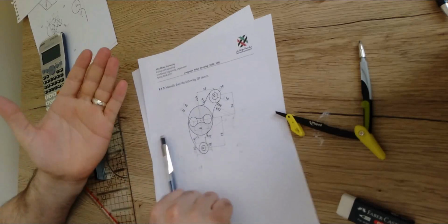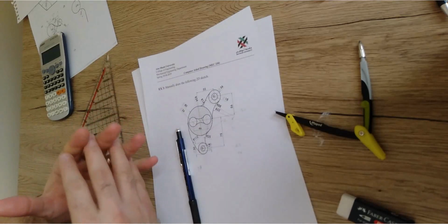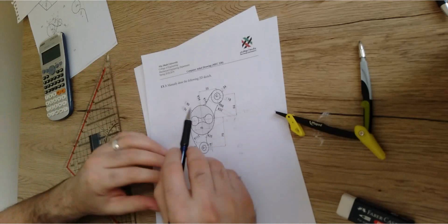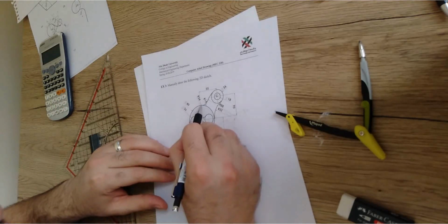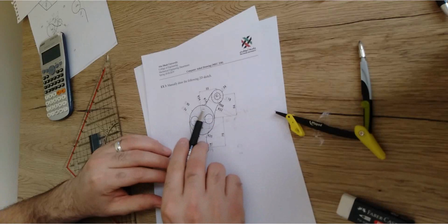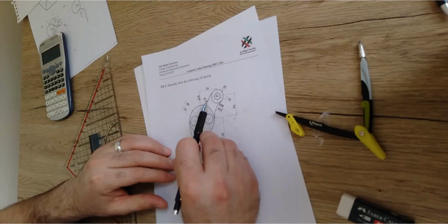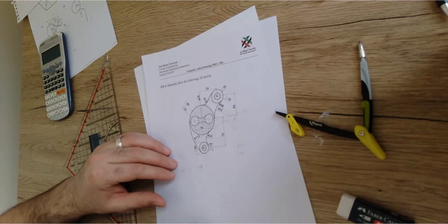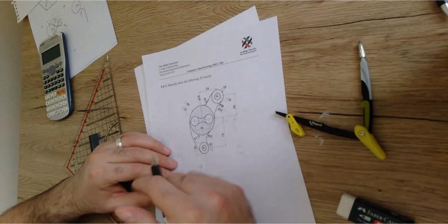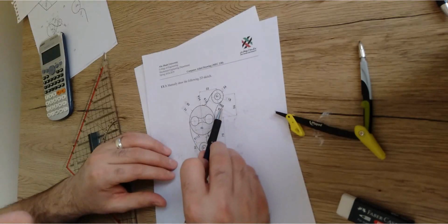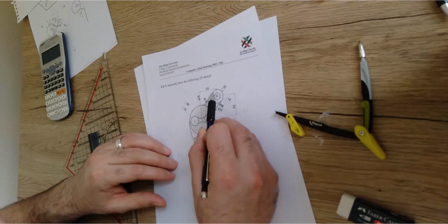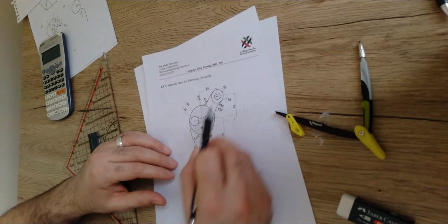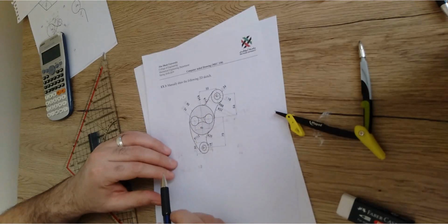But basically, to draw a curve that is tangent, for example, if I ask you to draw the curve which is the R16, this small curve, it is tangent from this side to this big circle, and it is tangent from this side to this curve, but I don't have this curve yet. Also, if I ask you to draw this R88, it should be tangent to the R16, and from this side it should be tangent to the big circle, which is the 36. Make sense?